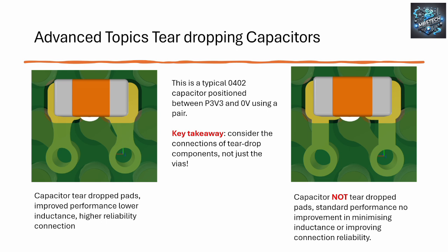So if I have an IC, for instance a SOIC, the track coming out the middle of the pad of the SOIC would have a teardrop effect. And I find I get far more reliable PCBs doing it that way. And it survives far higher mechanical stresses from what I've witnessed as well.